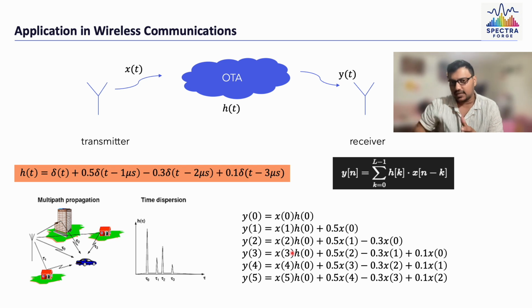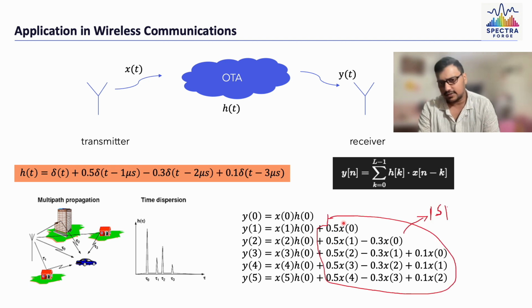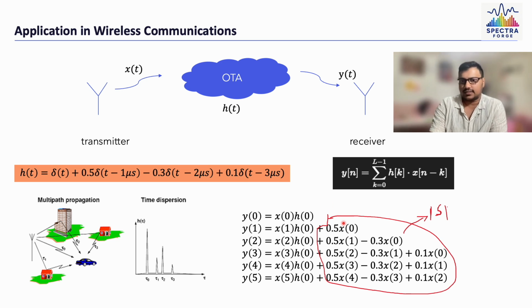But because of the spreading that's happening, because of the convolution, as I mentioned previously, if you have length L and length m input, the output is L plus m minus 1. So the sequence is spreading. Because of the spreading, here you are seeing ISI. So in wireless parlance, everything else other than the first row, first column, is considered as ISI, which means intersymbol interference. This intersymbol interference will distort my signal.